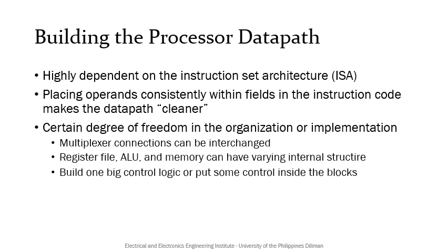There is also a certain degree of freedom in the organization or implementation of the data path. For instance, multiplexer connections can be interchanged. There is also no specific requirement on how the reg file, ALU, or memory has to be constructed internally as long as they adhere to the expectations or assumptions when the data path is constructed.